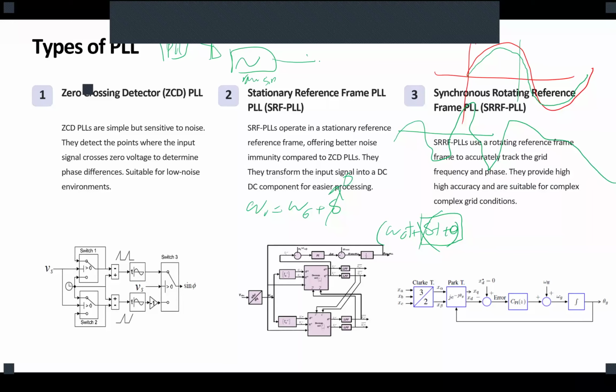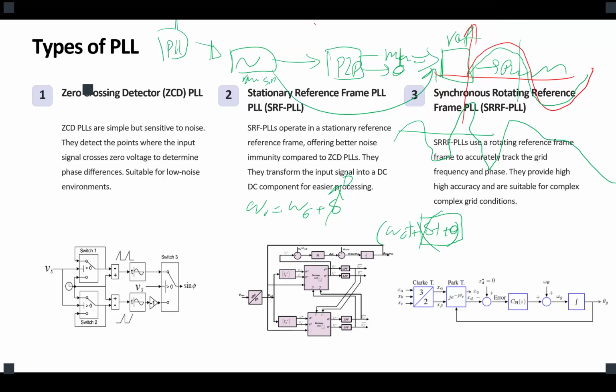Then this raw sine voltage goes to your PID controller, which sets the MA and the theta, applies them to that raw sinusoidal, and gives you your reference voltage for PWM. You see what I'm saying? So this is the situation that's going on in the control system. Are we good? Any question?